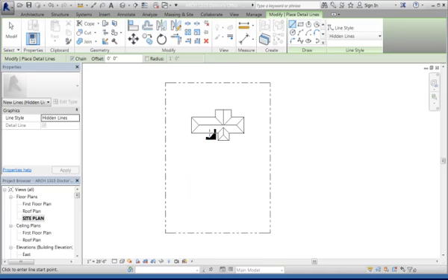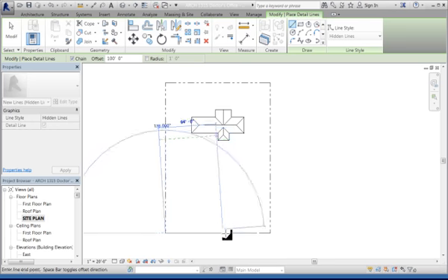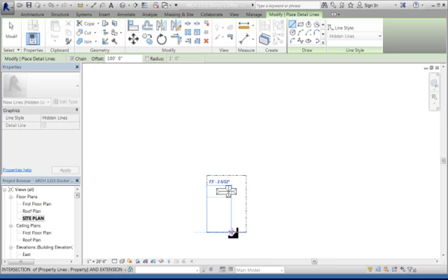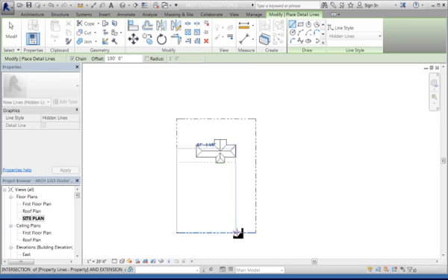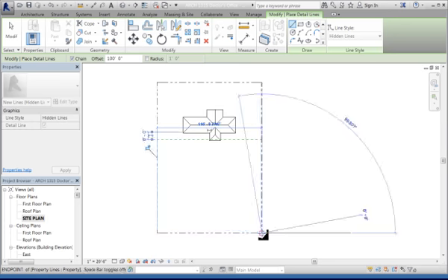So the easy way to do that is I'm going to make a line that's selected. I'm going to offset it 100 feet right there. Then I go here at this line and see it's making that setback line up there. If it was doing it on the wrong side, I'll show you. You just hit space bar and it'll pop to the other side, but I want it on that side. So then you go to there.